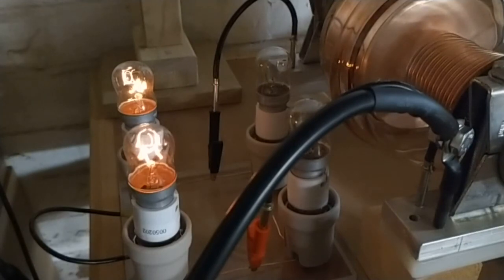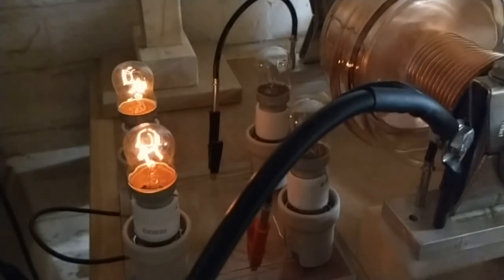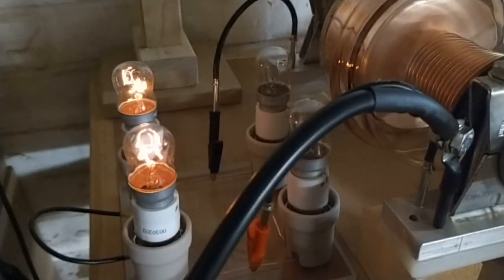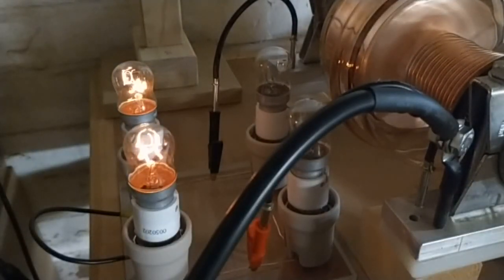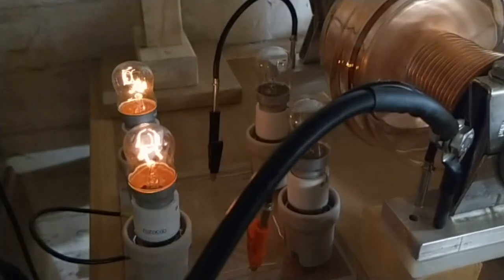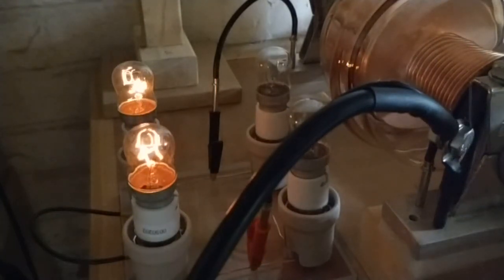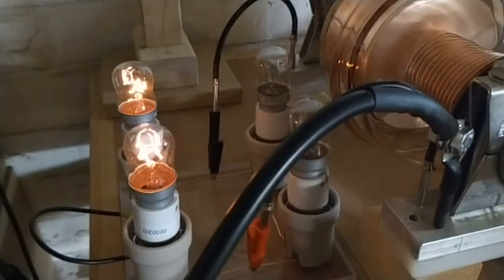Okay, so we have the two transmission coils, the transmitter TMT and the receiver TMT. They are tuned at the optimum point, like before, like we did with the linear oscillator. There is a high tension at the top end of both of the coils, but there's still very little power transferred because the spark gap is only creating or generating a small proportion of energy in the band that is actually being transmitted through this high Q system.